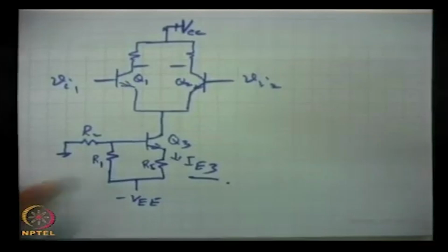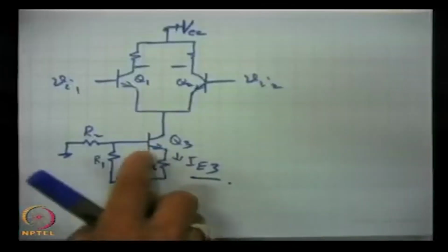So, this acts as a better constant current source, very widely used, because this point was essential, that a constant current source provides a constant current to the differential amplifier. This can be analyzed in a simple manner. We will be talking about that, and this can further be improved. This resistance R1 can be replaced with two diodes having identical characteristics as this emitter base junction. So, these are the points which we will be discussing, and then we will move further.